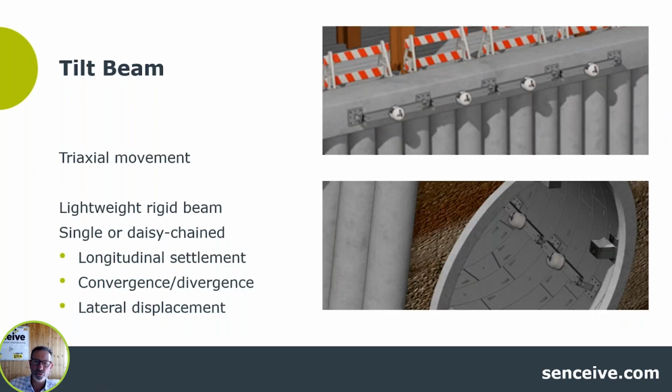Tilt nodes can be installed in a linear fashion, onto a beam, a tilt beam, and in this way applied onto this stainless steel beam, which gives us choices of different lengths. We've got joints that allow for thermal expansion, contraction, and we can use it, for example, where we're interested in looking at brickwork or masonry, where movement of individual blocks may not be representative of the structure as a whole.